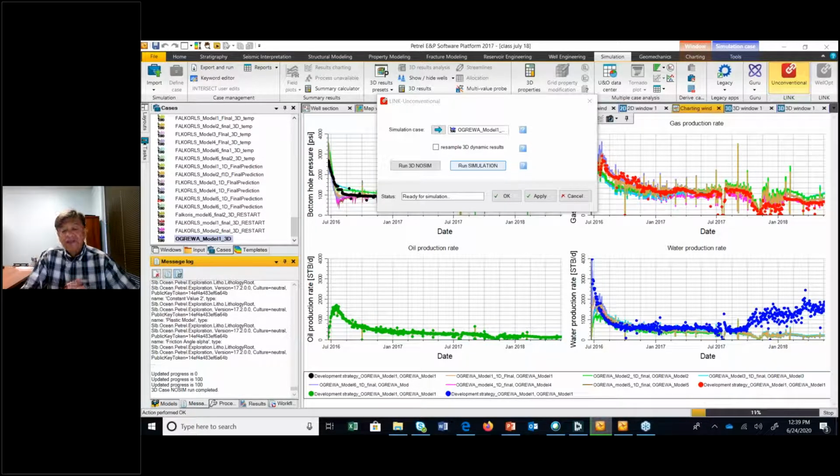Then it will take that information and calculate the compressibility of each individual grid block, because you need the compressibility of individual grid blocks so that you can calculate the speed at which the pressure wave travels. Remember, this fast marching method is based on the traveling pressure wave. Once you calculate the speed at which the pressure wave travels, it will generate the values of tau,